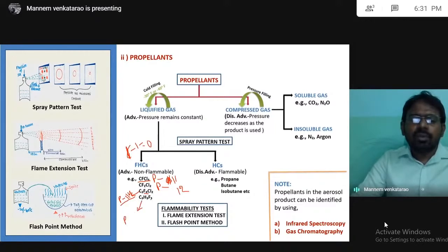Next, this one. This is a trifluoroethane. I don't want the nomenclature. I want only digits. Number of fluorine atoms, 3. First digit completed. Second, hydrogens. 3 hydrogens, 3 plus 1, 4. Next, carbon atoms. 3. 3 minus 1, 2. That's what is called 1, 4, 3. Likewise, you can give the digits.